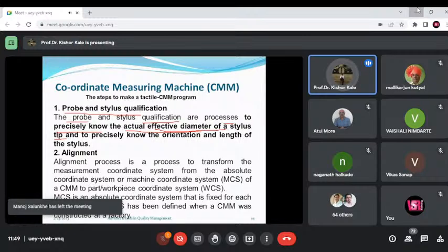Now, inspection frame and CAD reference frame, and then these are being aligned. You can see over here, the CAD reference frame is from the 3D geometry. These are the actual measured points in the inspection reference frame. The measured point set is obtained with respect to the inspection reference frame. So we know the point set of this. The nominal CAD model is defined in the CAD reference frame. This is nominal, meaning your ideal one.